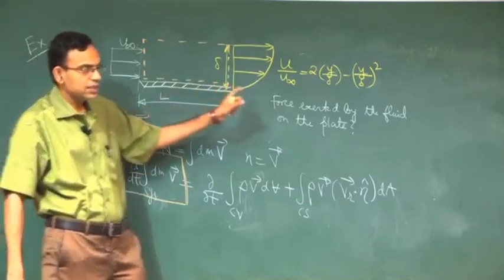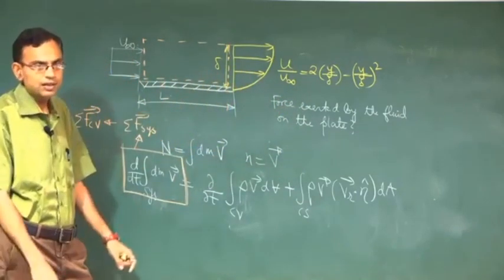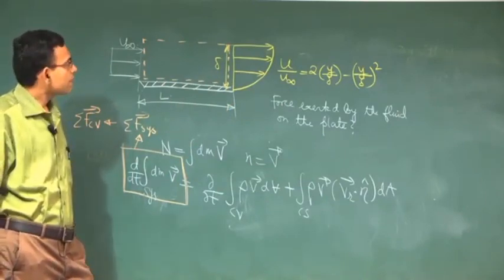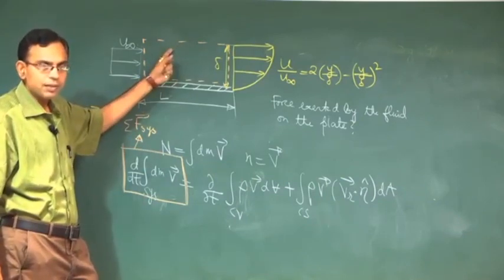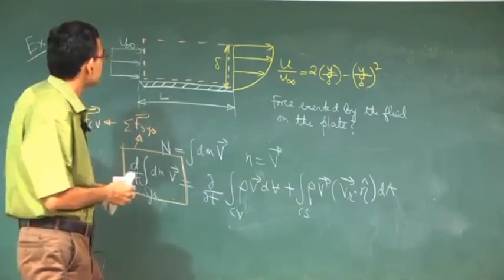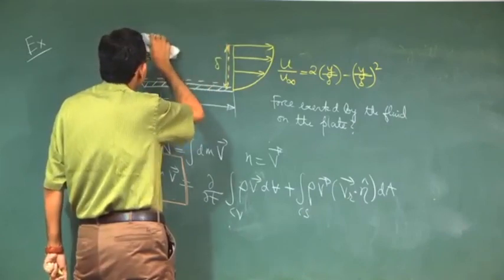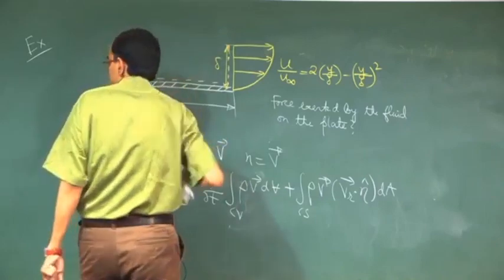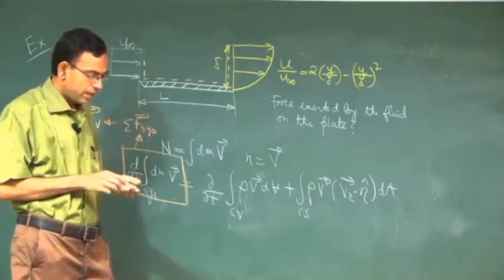Density is constant is our assumption, I am not writing it again and again, but it is a major assumption. Then that will add to the calculation of momentum flux, because if some mass leaves here, it will carry certain momentum along with it. So what can be the choice of the control volume instead of this, which will result in no flux of mass?